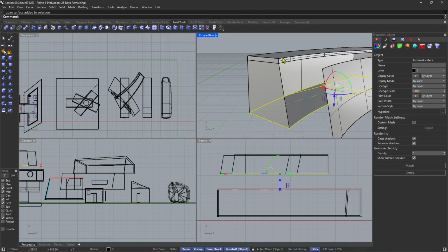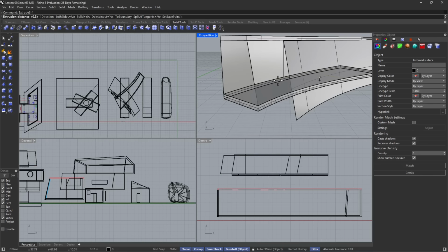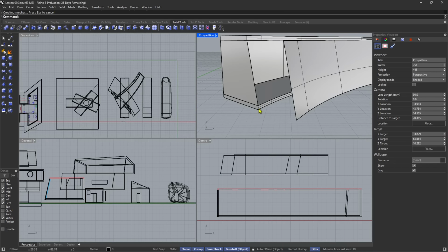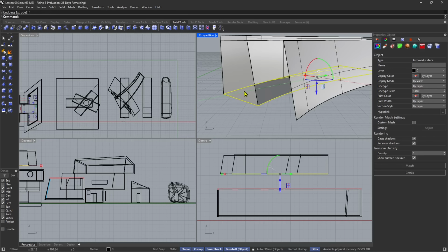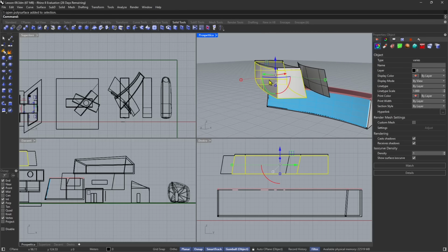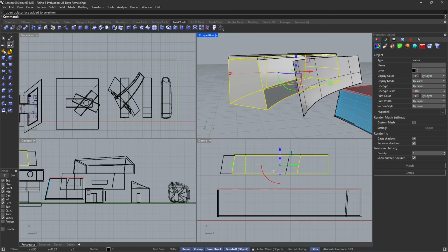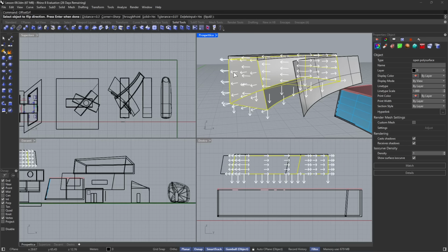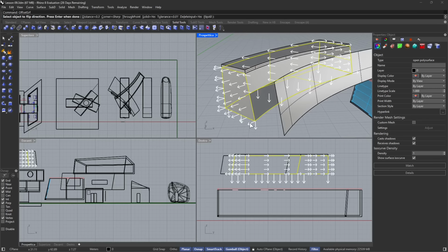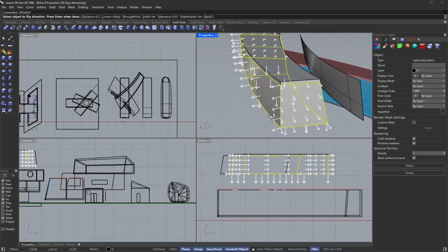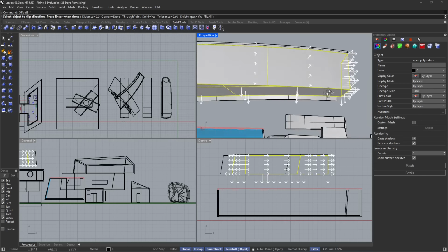So depending on what you have in mind, you need to choose the right path. And to maintain that line, for example, also here, if I go like this, again I will have another change in this straight line. So instead, I join all the walls together with the roof and the pavement, and well, we cannot use extrude. We can use offset. Offset surface is perfect for this because you can see all these arrows, they represent the normals, and all the normals of this extrusion are oriented outward.